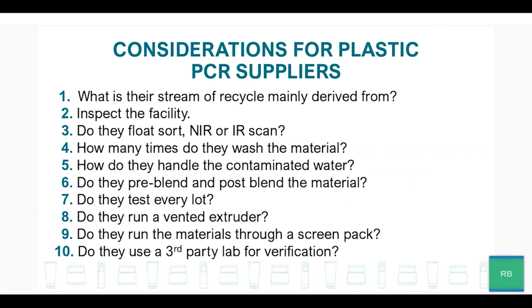Do they pre-blend and post-blend? Do they test every lot in-house? Do they run a vented extruder to pull off volatiles? Do they run the materials through a screen pack to remove as many contaminants, such as carbon or aluminum? Do they use a third-party lab for verification for certain tests, such as food contact?